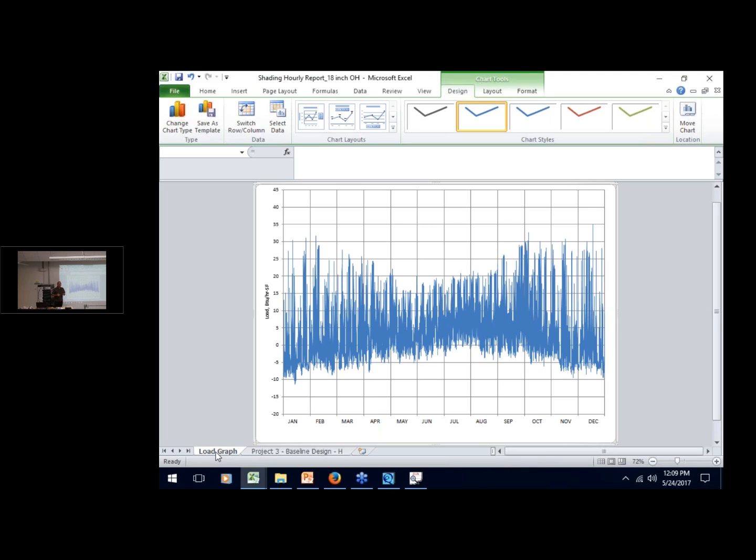And sometimes you have to hold the hand of the design team. I'll usually ask them right up front, what are your design questions? If you could ask this model any question that's out there, what would you ask? And half the time there's no response. So then I start queuing it up. Are you interested in solar load? Are you interested in how much glass is too much? What type of glass makes the most sense? Are we interested in sharing with the contractor or the engineer what their peak loads are? I don't want a chiller that's twice as big as it needs to be. Those kinds of things.